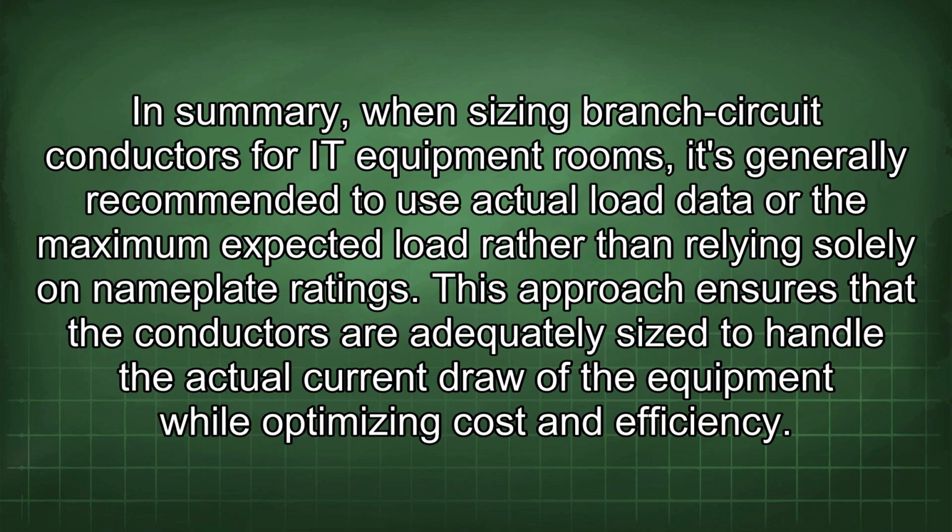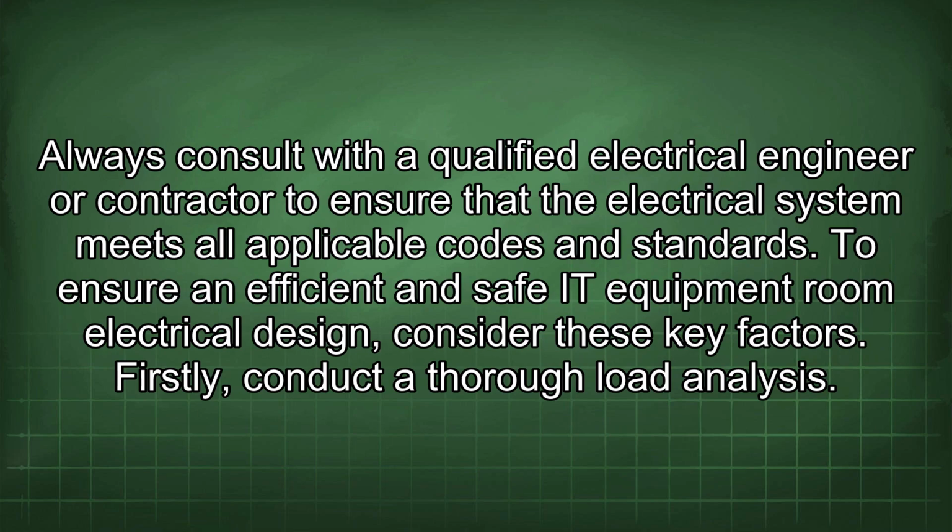In summary, when sizing branch circuit conductors for IT equipment rooms, it's generally recommended to use actual load data or the maximum expected load rather than relying solely on nameplate ratings. This approach ensures that the conductors are adequately sized to handle the actual current draw of the equipment while optimizing cost and efficiency. Always consult with a qualified electrical engineer or contractor to ensure that the electrical system meets all applicable codes and standards. To ensure an efficient and safe IT equipment room electrical design, consider these key factors.